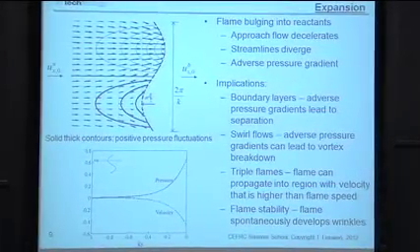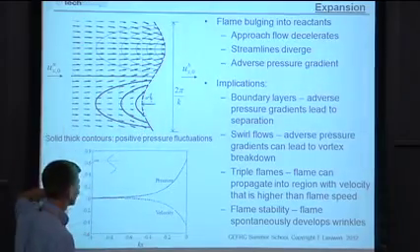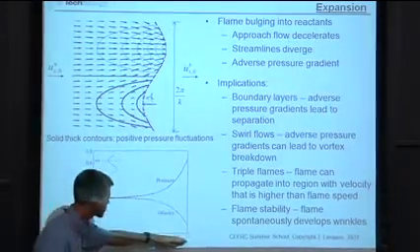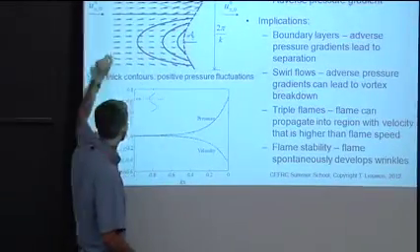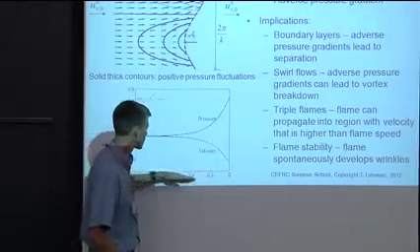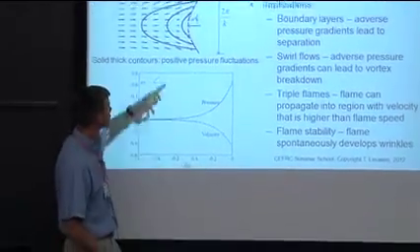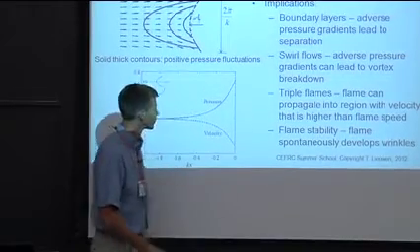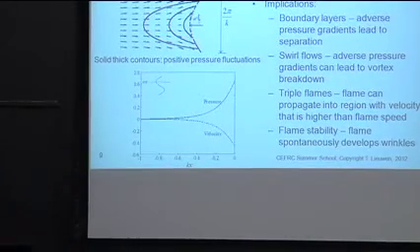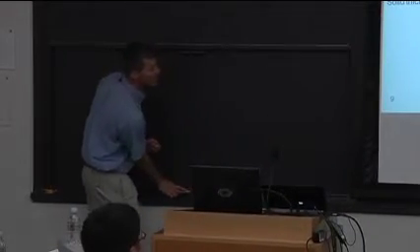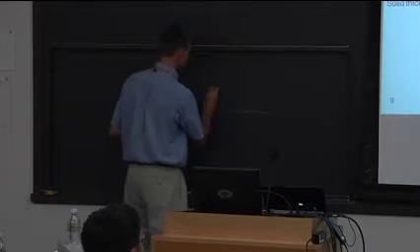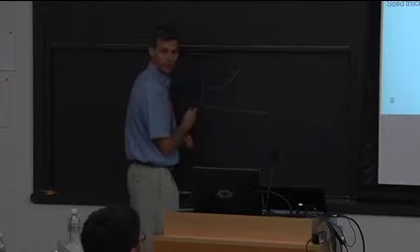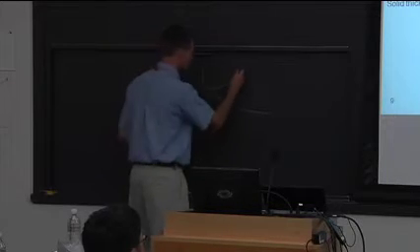If I'm following a streamline through here, what I would see is, actually I have it down here, where I'm plotting the pressure and velocity along this line right here. That's what's being plotted on the y-axis. This is dimensionless distance. K is the wave number of the disturbance. I'm plotting it all the way up to the flame. I should have drawn it farther. In fact, I will on the board, now that I know how to use this device over here. If I were to draw the pressure, it looks like this. It rises, and then what happens at the flame? It drops like that.